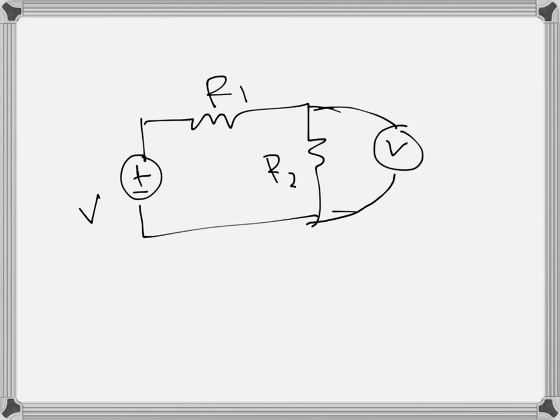Now the voltmeter, an ideal voltmeter, is supposed to have an infinite resistance, so there will be no leakage current through the voltmeter. Because if that happens, the measured voltage will not be accurate, there will be some error. But of course, no element is ideal, no apparatus is ideal. So every voltmeter comes with a sensitivity.